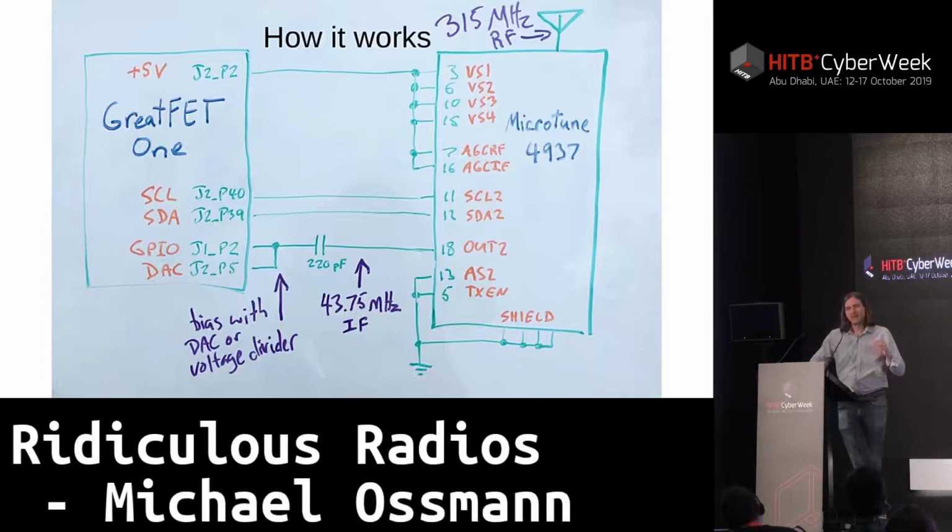In this case, we wanted to make sure that we could get the GPIO pin to trigger. Now, a general purpose IO pin has some voltage threshold. You have to exceed some upper threshold in order to flip it to a 1. And then you have to drop the voltage below some lower threshold in order to flip that input to a 0. And those thresholds aren't exactly the same point. They're some distance apart on the voltage scale, some amount of voltage that you have to exceed in order to get this bit to flip repeatedly.